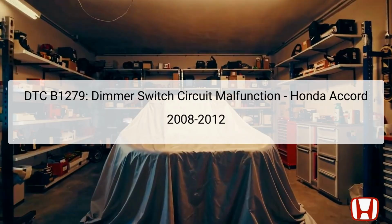The DTC B1279 indicates a malfunction in the dimmer switch circuit of the Honda Accord models from 2008 to 2012. This error code signifies that there is an issue with the functionality of the dimmer switch, which is responsible for controlling the brightness of the vehicle's dashboard lights. The dimmer switch is typically located on the steering column or directly associated with the headlight switch.